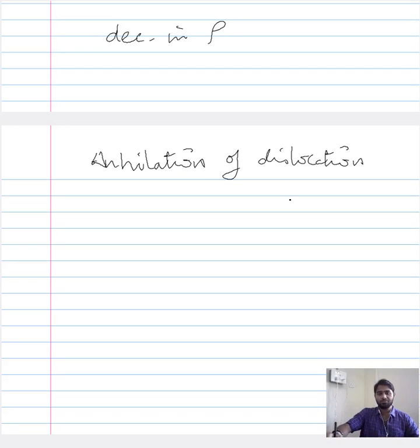What we have in terms of edge dislocations are positive and negative edge dislocations. Now, when these positive and negative edge dislocations travel in the same plane, under certain conditions, when they interact, they annihilate each other. For this annihilation to occur, we need the positive and negative dislocations traveling in planes that interact with each other. That possibility is rather small, or trivial, under ambient or room temperature.